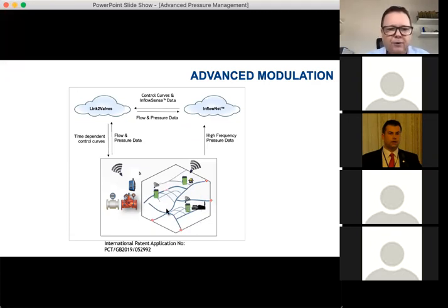So now, if you have a system where you have multiple pressure loggers in your network, this is actually a system by Inflomatics, where these sensors are actually looking for transients. So there are transient loggers that are helping to identify where you have transient problems in your network, but they can also help to monitor pressures across a zone and identify where the critical points are and how the critical points move.